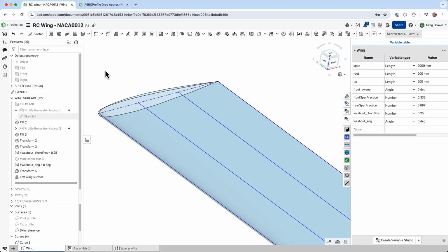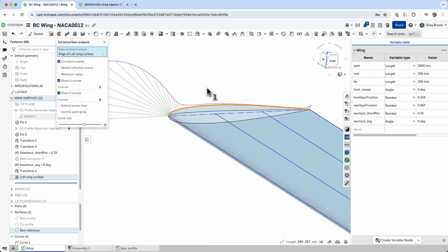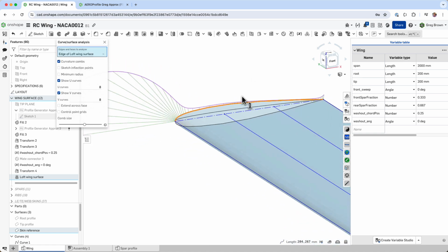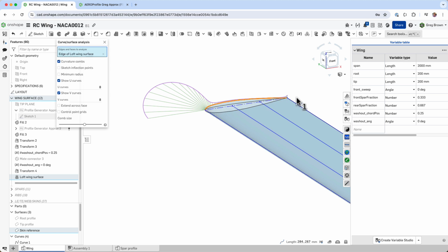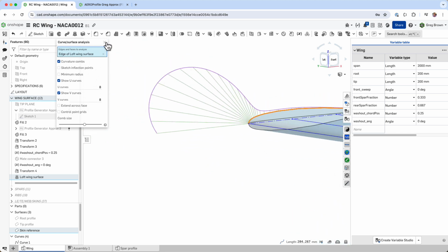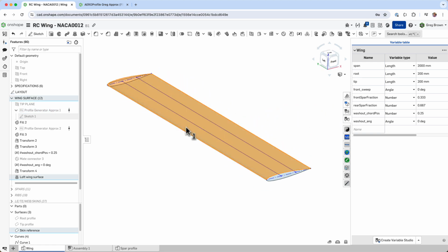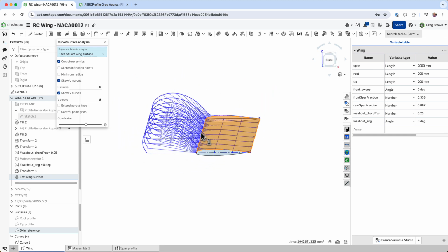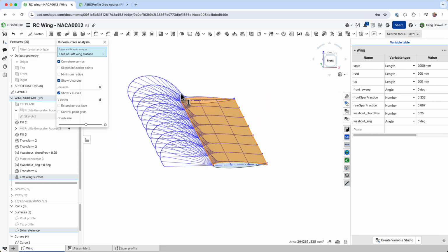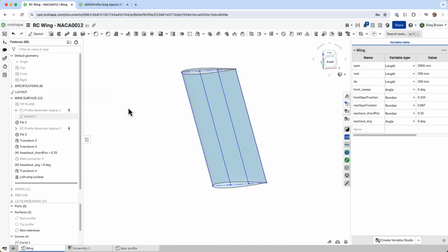Anyway, what it means is that if we have a look at the quality of the curves that are now on this profile, they're very smooth. I've actually used a degree 5 curve in here, which then fit through or approximated the underlying points. Upshot is that we've got a nice curve to play with, and because this curve is going to generate so many things downstream, I want that as good as possible. Of course, if we look at that overall, that's naturally the way that loft works, and the way that these curvatures travel downstream. So I use that for the tip and the root.